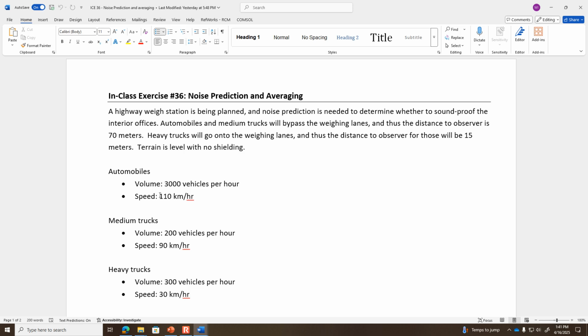So that's automobiles. Okay, next, we're going to draw a line from the A1 intersection point through the volume of 3,000 vehicles per hour. So take your ruler and find the A1 point and 3,000 vehicles per hour and just draw a line connecting the two.